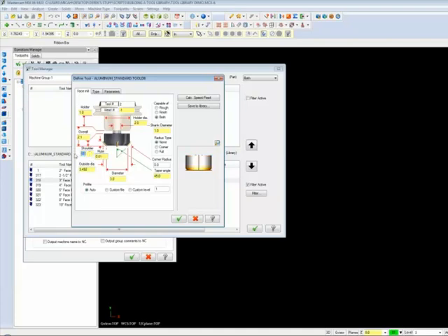The tool is 1 3/4 inches tall, and overall tool length out of the holder will be about 1.875. The outside diameter is 3 inches, and the taper angle will be 0 degrees.